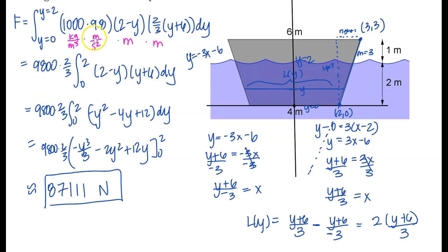So if we look at what's going to happen, meters, meters, meters, and meters cubed will cancel. So we're integrating kilograms per second squared over meters. So y equals 0 to y equals 2 are meters. When we integrate, we're multiplying the units of the integrand and the units of the limit of integration. So we're multiplying kilograms per second squared times meters, which is equivalent to what a newton is. So we do end up with the unit of newtons here.